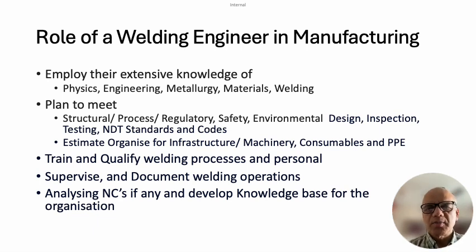A regulatory requirement will be that a boiler cannot be heated beyond 400 degrees centigrade, or a boiler cannot withstand more than 200 bar pressure, or what will be the minimum safety factor, or which are all the approved materials to be used in this region of the world.